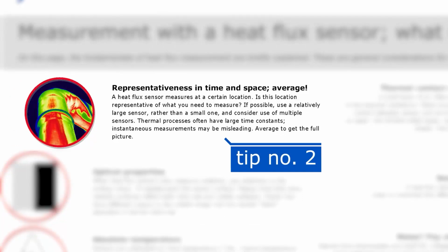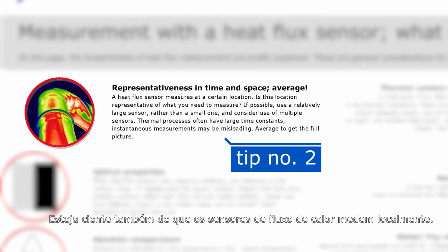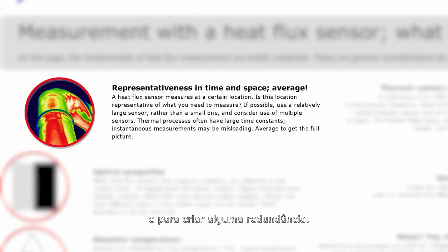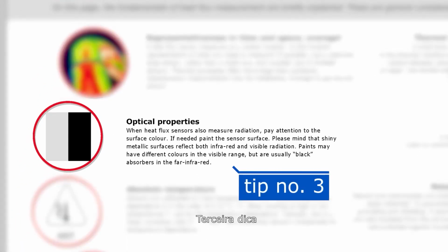Tip number 2. Also be aware that heat flux sensors measure locally. Most systems employ multiple sensors to get a better picture of the variability from one location to the other and to create some redundancy.